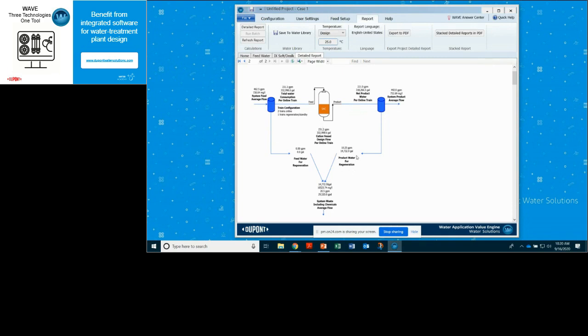Subtract off the number down here, the product water for regeneration, and that gives you the net product flow per train. So this set of numbers in the center is what's happening at the train level, and the 3 numbers on the outside are what's happening at the system level, averaged over multiple cycles, as opposed to what's going on during the middle of a cycle.